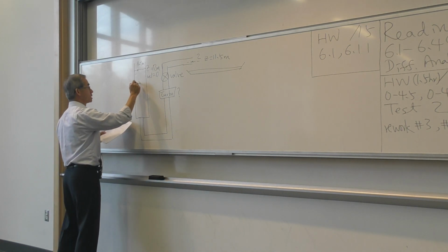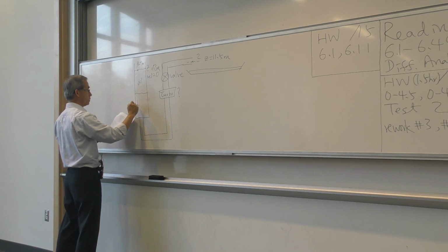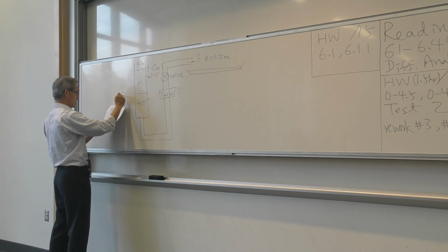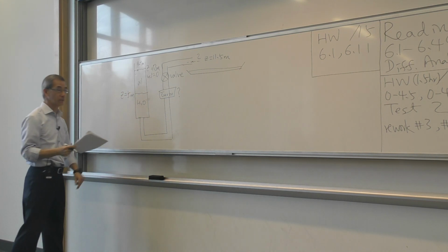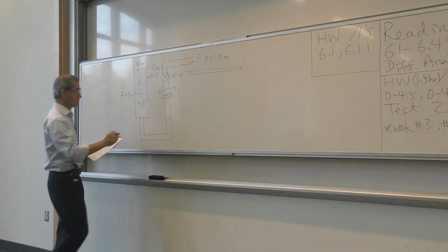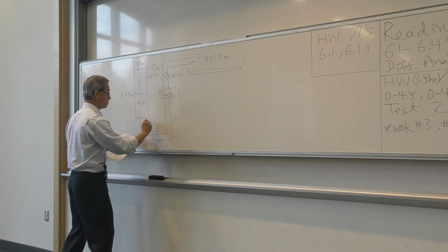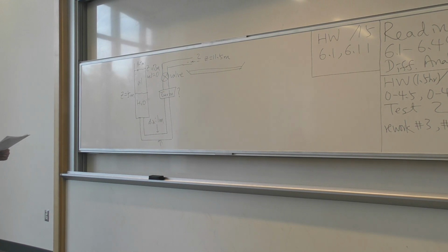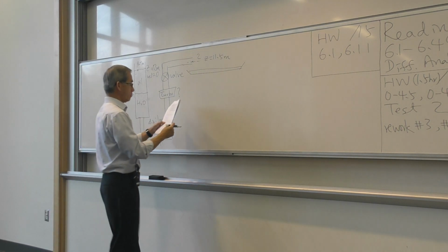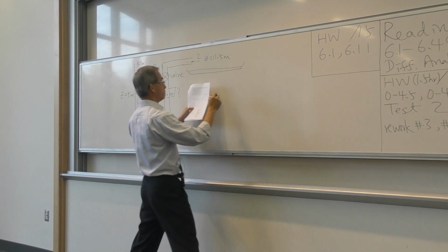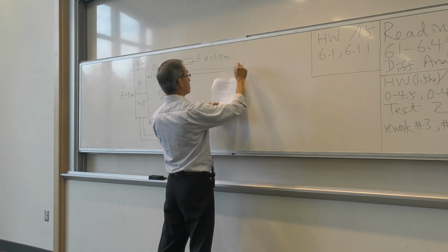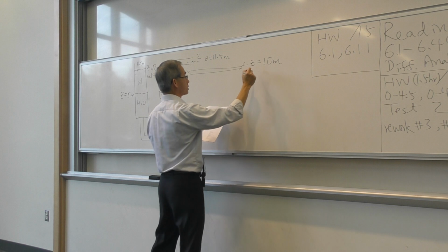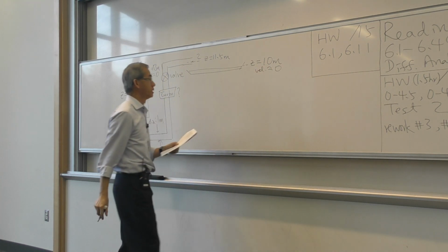And the fluid in this reservoir consists of two different types, and there's a reason why there are two different types. Because the density is not the same, and you have to be very careful how you apply the energy equation. So we have oil and water. The pipe diameter is huge. It's 1 meter, so it's a gigantic pipe, not your typical small pipe. And because of that, you can have multiple answers due to how you approach the problem. The reservoir surface where velocity is negligible is 10 meters.